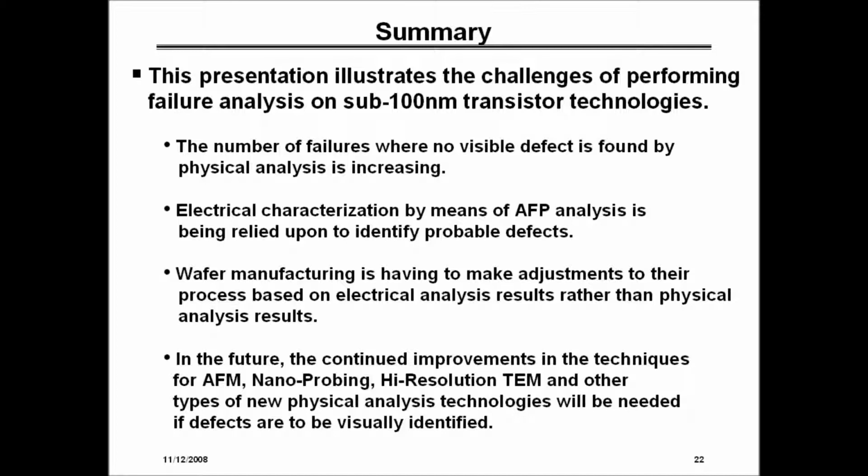The ability to probe packaged parts is somewhat difficult because of access to the material around the sample within the package. So currently on our systems, it's difficult to probe a packaged part, but it's not impossible. Typically, users would depackage the device. I think Randy would confirm that. Typically it would be a depackaged device down at metal or contact, and then probe directly. Yes, that's correct for the most part.